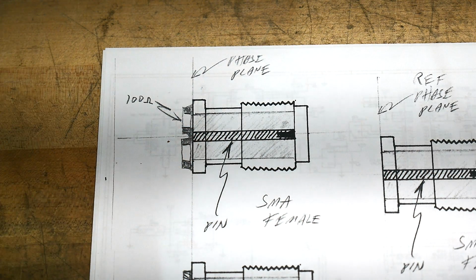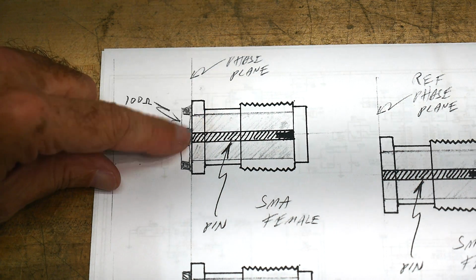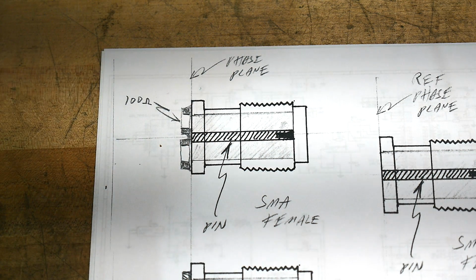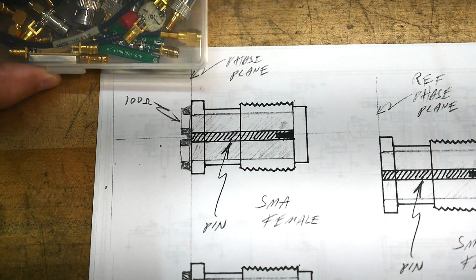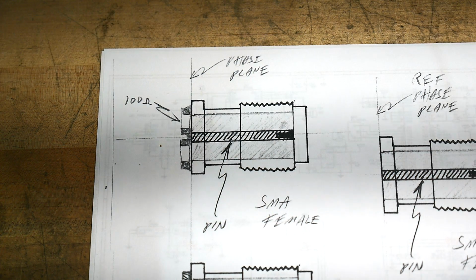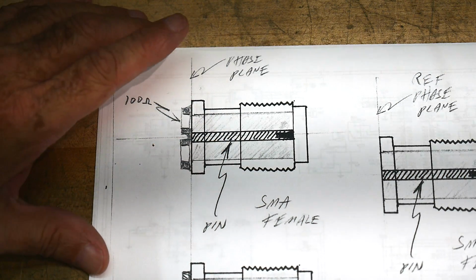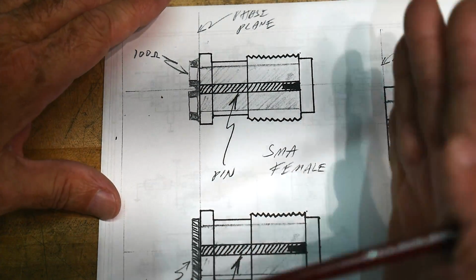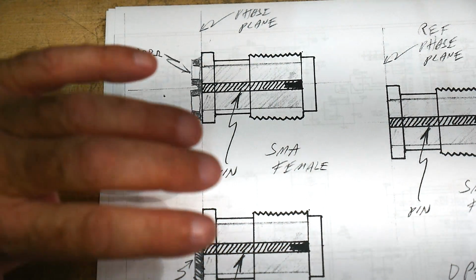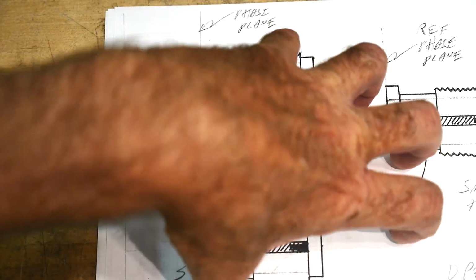I'm not sure how much phase information is actually taken from the load calibration. And if you think about the cal standards you were given, I think you can convince yourself that the open and the short have similar reference planes, but the actual load does not have the same reference plane, so I'll let you think about that. But this is basically the idea. There is some reference plane. Now, if you get a $100,000 40 gigahertz VNA, you're talking like $4,000 or something just for the cal standards.